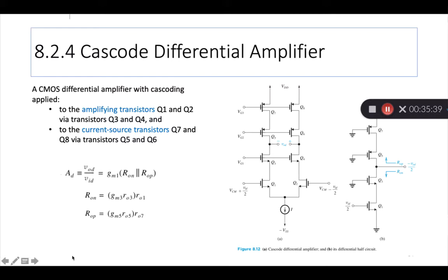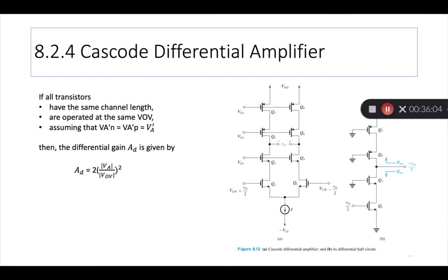But we know that by this arrangement and spending so much money on all these extra transistors, your gain goes up by almost a square factor, right? If you have a basic gain of, let's say, 10, with all this arrangement, you can get almost 10 squared, or close to 100. Where 100 is too much for these, but maybe it goes from 3 to 9 or something. Okay.